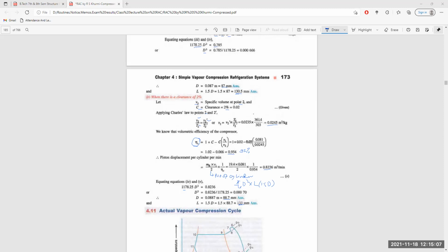evaporating process itself. We are using a refrigerant which is in liquid state in some portion of the cycle and in vapor state in some portion of the cycle, and we are using its latent heat of vaporization and latent heat of condensation for extracting heat from our refrigerating chamber, which is housing the refrigerating coils surrounding it.